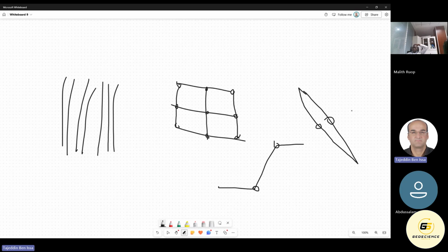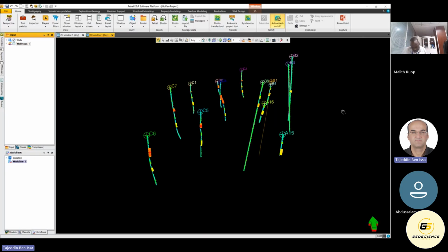Fault boundary is not recommended because you will do the fault model with uncertainty in the angle and the displacement magnitude of the fault. So it's always preferred to work with fault sticks or fault polygons, which are usually exported, or which are the result of converting fault sticks into fault polygons.